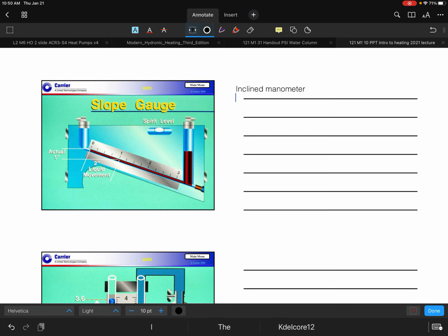I think incline manometers are generally very good for low pressures. When we measure airflow in a system, we've got manometers that can read 1/4 of an inch and fractions of the 1/4 of an inch that are incline manometers. It's all in the way that they design them. This incline manometer, without a doubt, is really the gold standard when it comes to that, for the most part. For measuring air pressure, measuring duct pressures, it can be excellent.